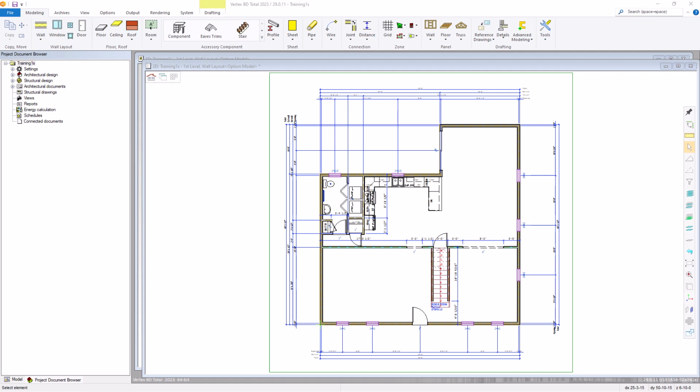Earlier in our project, we modeled the ceiling material and floor coverings. These materials will be added to a material report. The room function can be used in place of modeling these materials. The room area and perimeter information generated by the room function can be used to calculate these materials and reduce modeling time. This can be helpful if the main purpose of drawing the model is to generate material reports and you do not plan to use the model for renderings or presentations.